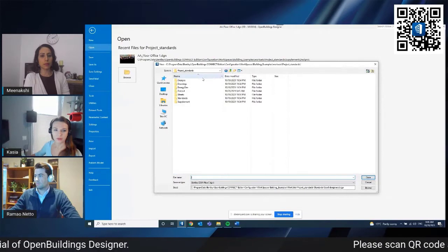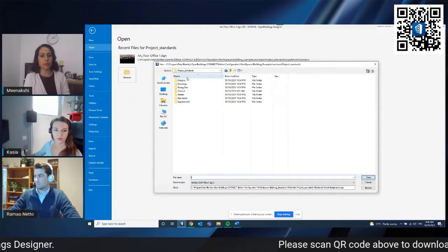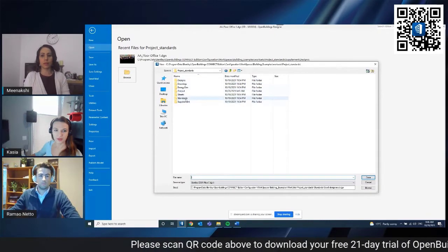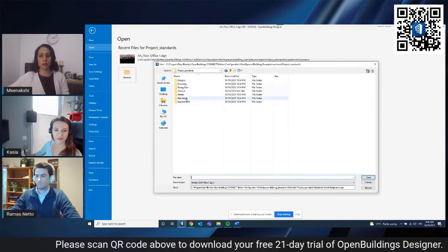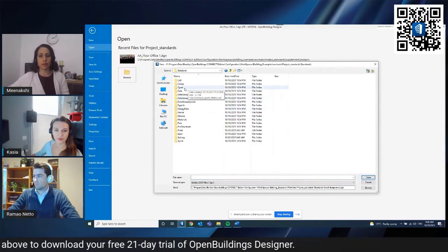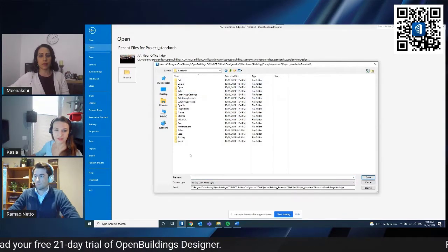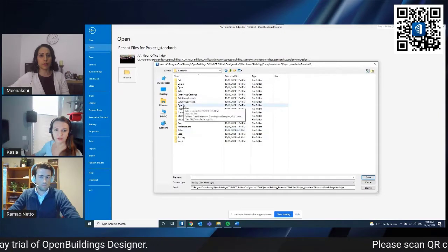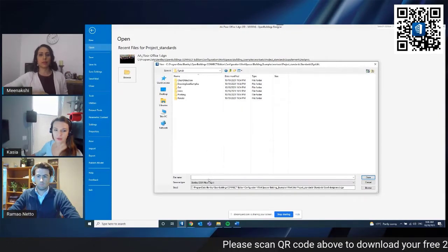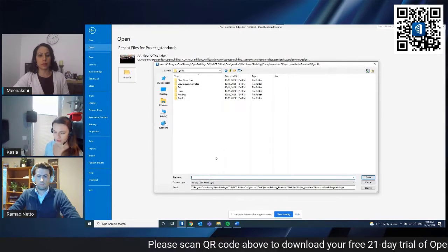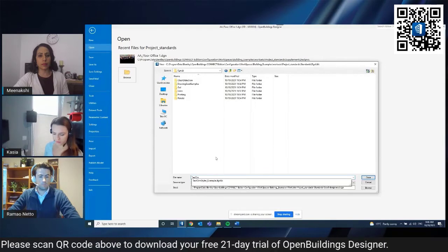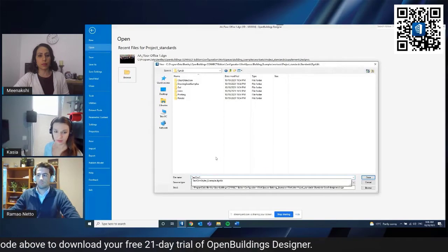Every workset has those default folders prepared, and in this template workset that I mentioned, we have all those folders. And in the standards folder, in the DGN lib folder, I can create a new file that will control the text and dimension style.